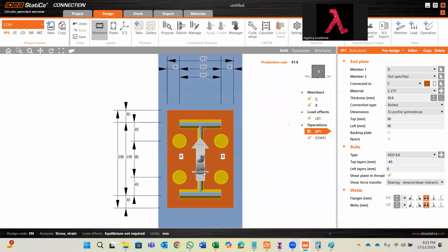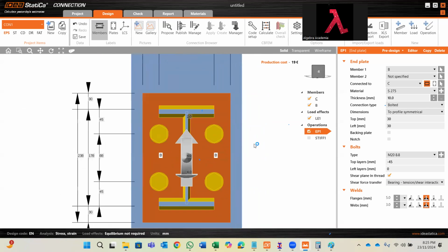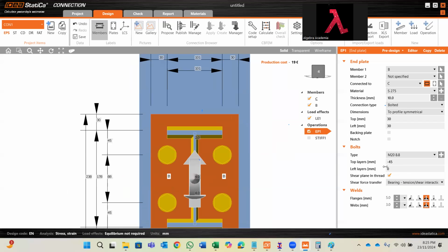Here it is not a problem, because the edge distance will have an issue mainly in the anchor bolt, which is 40 to 50 millimeters, because there the pull out failure will be happening frequently. So here you don't have any issue. You can maintain minimum 1.25 times the diameter of the bolt. So our 30 to 40 millimeters you can keep. Okay. So I'm just keeping 30 millimeters as it is.